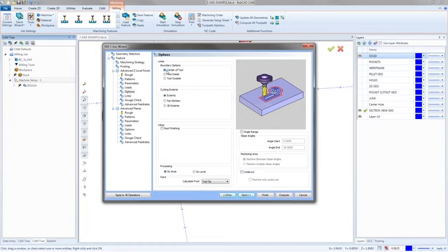So you always have to remember there's another half of your tool sticking out on the other side of the boundary. That's partially the biggest reason why I tell everyone, when you're picking your 3-axis geometry, to always pick the entire part. Because if all you pick is a surface and there's a wall on the other side of that surface, BobCAD's not looking at it. It's going to run right through it if it feels like it. So make sure you're always picking the entire model for your geometry. There will be times you can get away with picking just a surface, and a lot of people do. But for the most part, the best rule of thumb for geometry selection for any of the 3-axis is just always pick the entire part.